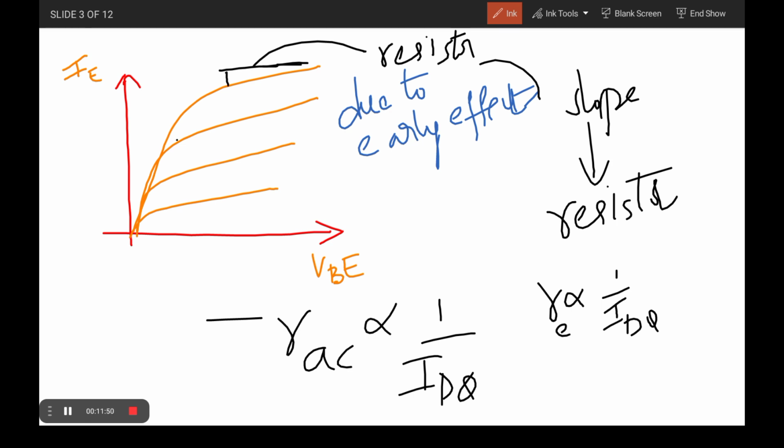The curves represent a constant value, and this constant value is the IE current, IE1, IE2 and IE3. That means the emitter current maintains a constant value. Wherever a network or any circuit produces a constant current value, that is generally called a current source. That is why the transistor represents like this. If you observe very clearly from these two points, you have some idea about this configuration.